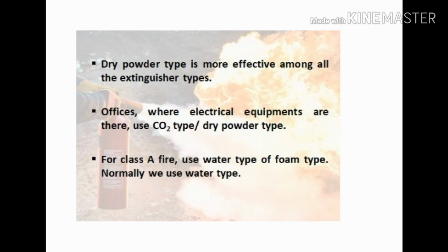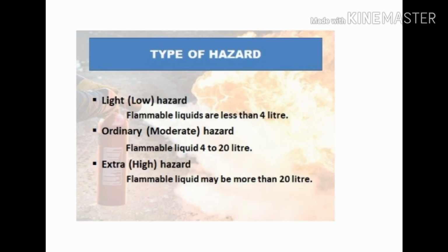Dry powder type is the most effective among all the extinguisher types. Offices where electrical equipment is present should use CO2 type or dry powder type. For class A fire, use water type or foam type. Normally we use water type.